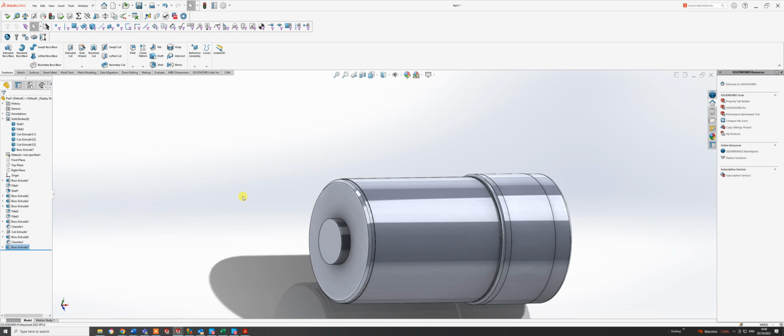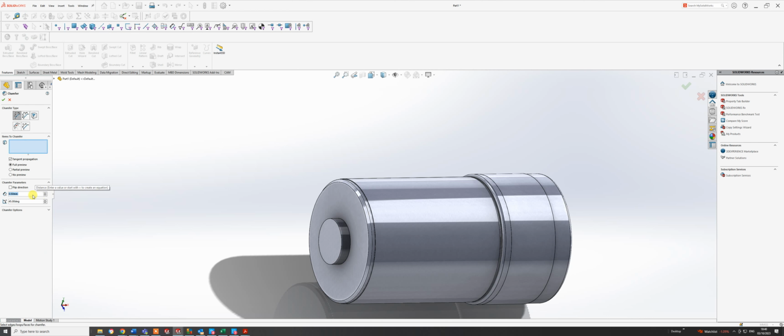And again I'm going to put a 0.3 chamfer on that, so go up to fillet chamfer. I don't want the 0.5, it's too big. I want 0.3, and it's just that one there.